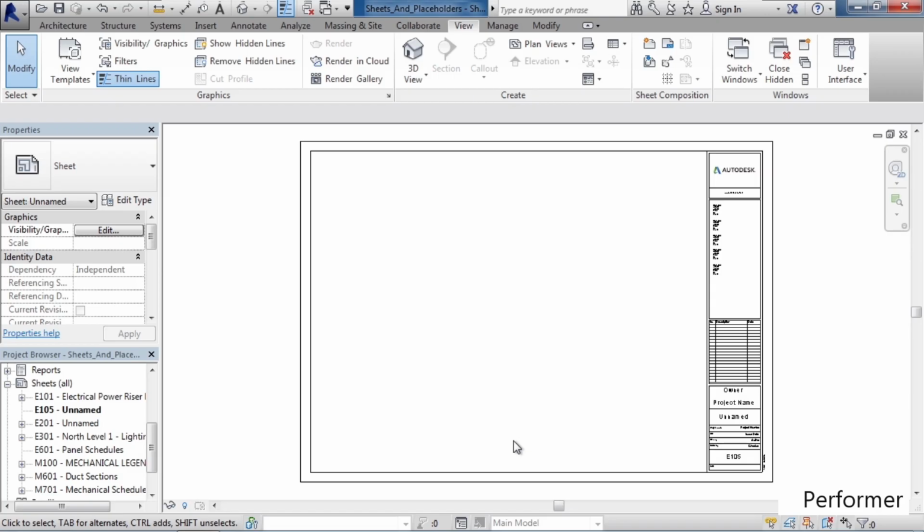Therefore, we need to add that text to the sheet list. This is known as a placeholder. That placeholder could later be converted into a sheet if we wanted to put that detail in Revit. And lastly, we looked at creating a sheet.